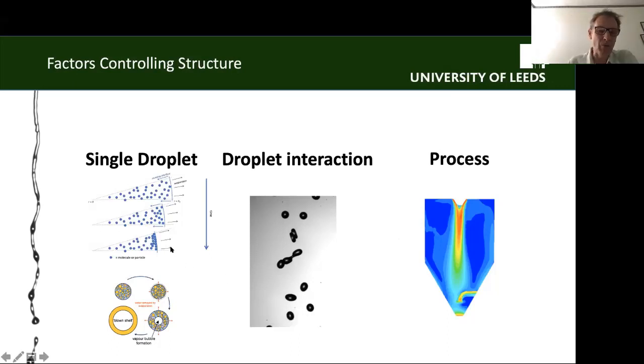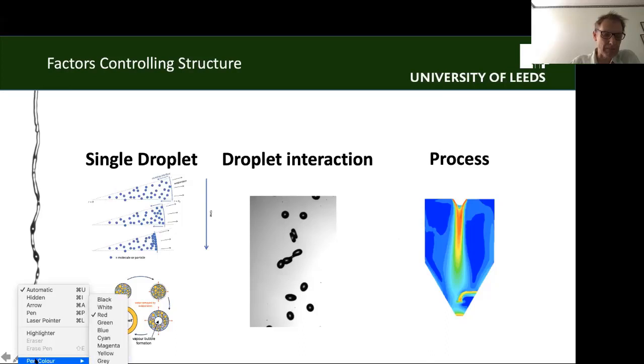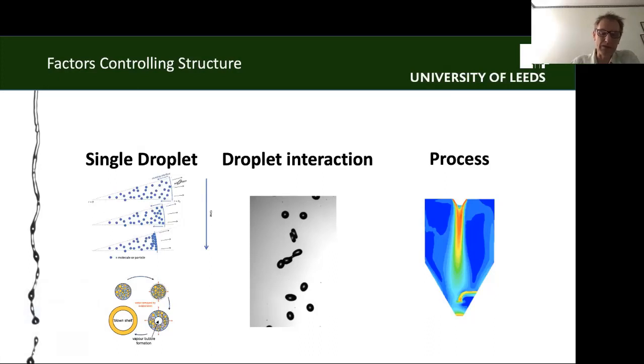One thing to think about when we're drying single droplets is there's a lot of complicated physics going on when we dry a droplet. We have the conversion to a solid, so the phase change, we have various concentration gradients that are established in the particle. So as a particle evaporates, the solute, the molecules in there which aren't evaporating, can get concentrated, and typically does get concentrated at the surface, and that drives a lot of the behaviors we see.